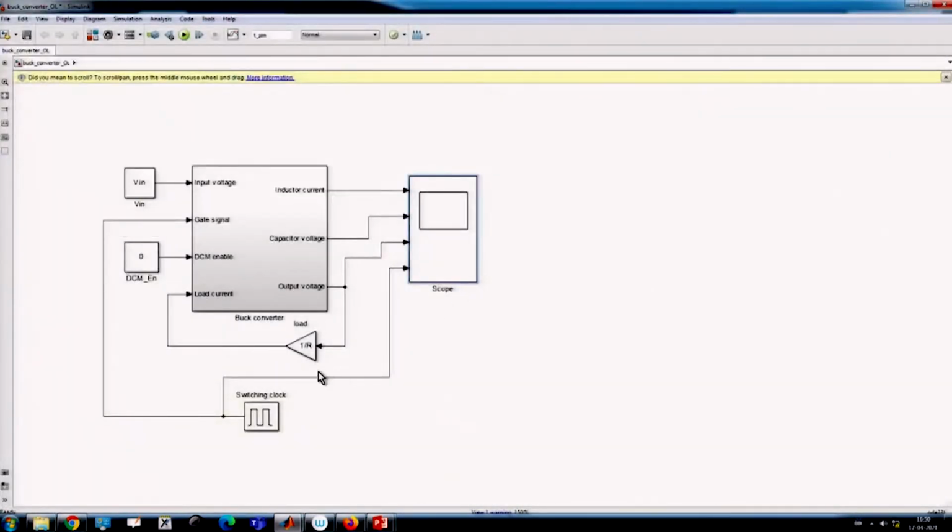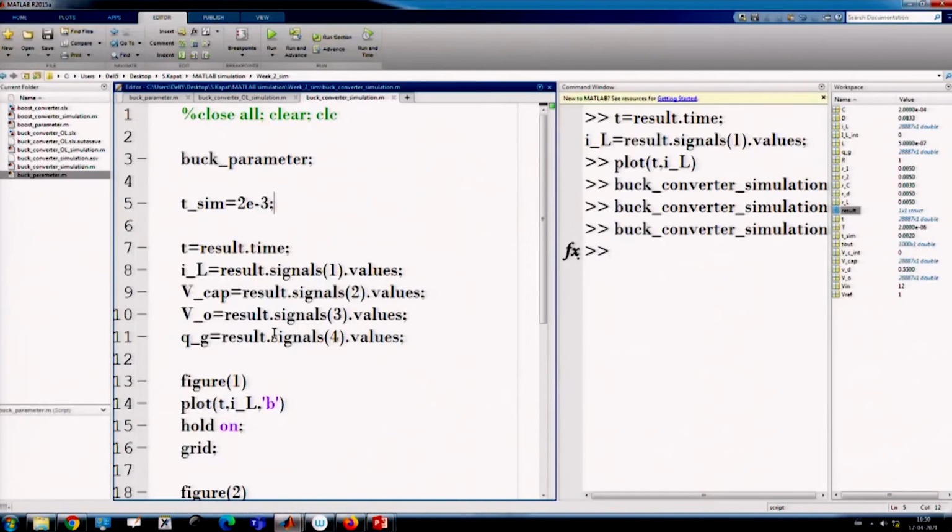Then how do I change the resistance value? Okay, next question. Doing all these things, you have to go back and forth to the simulating file, make changes, check there, take the values. Why should you do that? First of all, if you want to plot in Simulink, that itself will take time, because Simulink plotting while it is running will actually take more time than if you run it and plot after the simulation is over. You can store it. So this is possible.